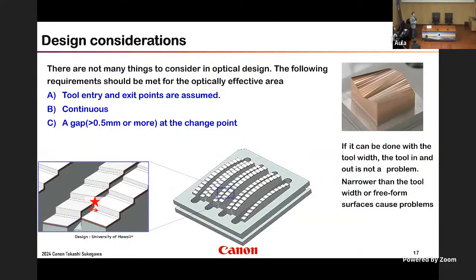This looks like a complex multi-faceted surface, a monolithic mirror, but you can see we can cut in this direction with each column slightly isolated. So we can make this kind of optics as one piece in our machining, and single point diamond cutting is allowed. This kind of shape is easy because it is in, out. So no restriction. This kind of shape makes us very happy. Anyway,